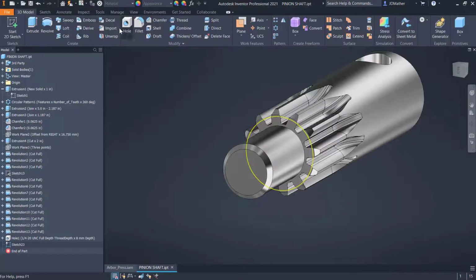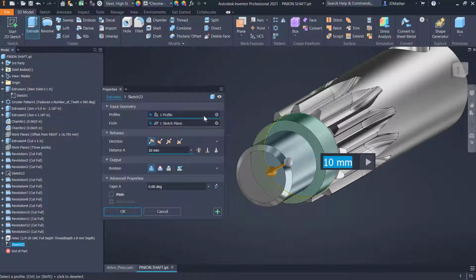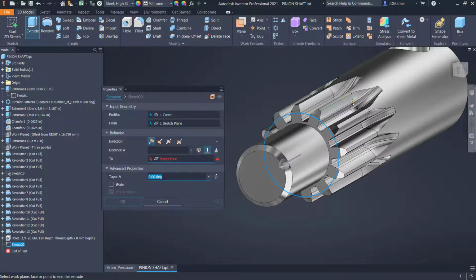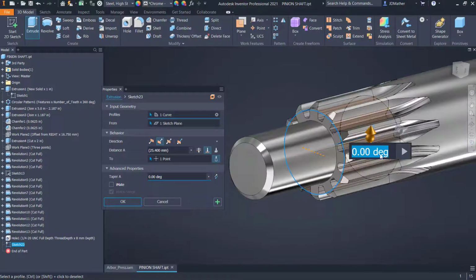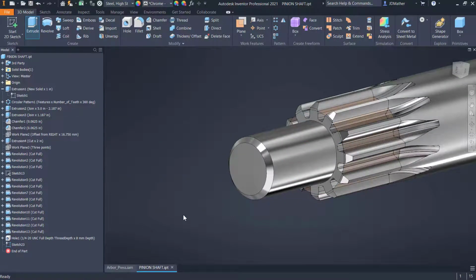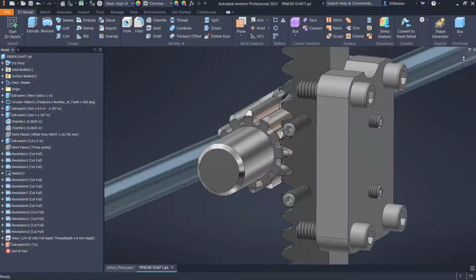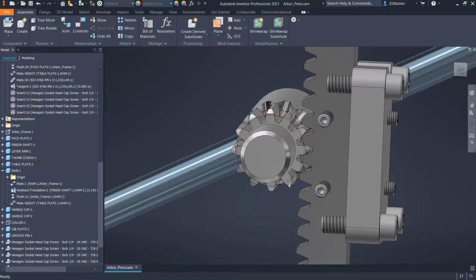And then I'm going to extrude that, but I don't want to add any mass to this part, so I'll extrude that as a surface body. So I'll change it to surface body, and I'm going to tell it to go up to, say, this point right here. So it's going to extrude that as a surface back to there. That distance really doesn't matter, just so that we have that cylinder. I'll save this file and I'll go back to the assembly. So that gives us the pitch diameter for the pinion.